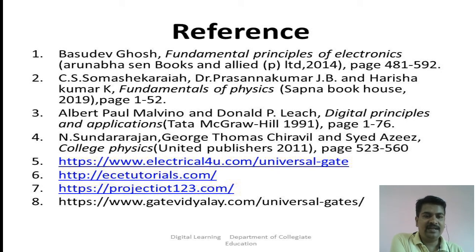Then we came to the POS form, understood the maxterm and how to write it, and learned how to write a POS equation. So overall the video is about writing both SOP and POS equations.